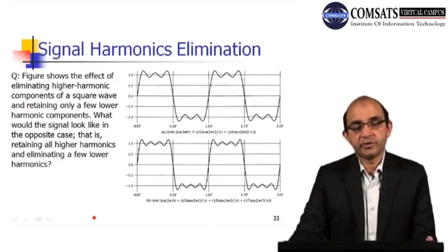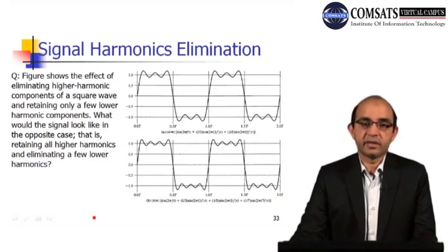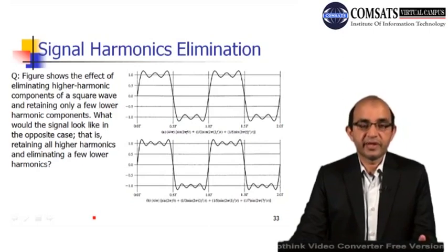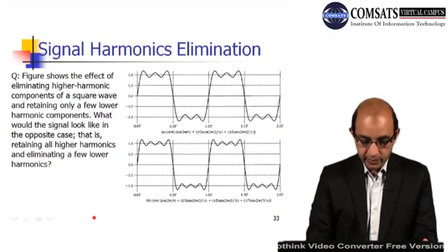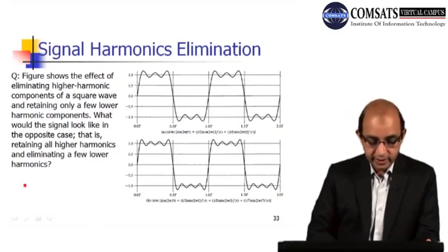Normally I will take the fundamental frequency, that is f, then its first three harmonics, 3f, 5f, and 7f, because most of the energy is contained within those lower order harmonics, right?